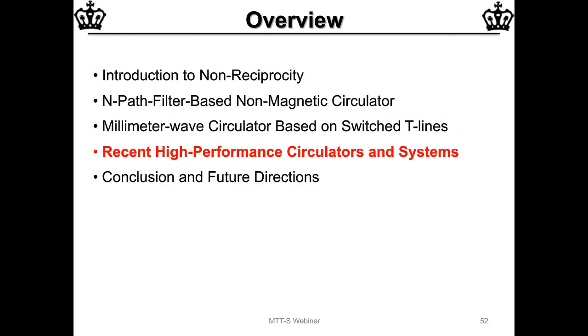So these were our two initial works in this space. The first showed that it's possible to build circulators on chip with a switched capacitor circuit, and the second showed how you could translate that idea to higher frequencies using switching across transmission lines. Since this work, we've made several new generations of circulators with improved performance.